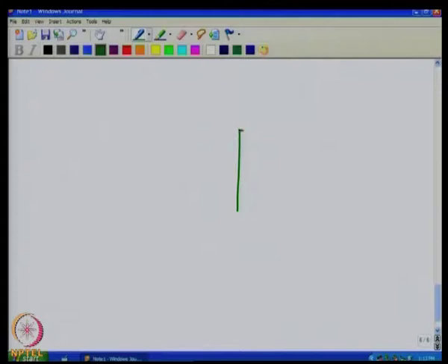For the resistance case, we just saw that the drops across the resistance can cause a functional problem in the output, where a current flowing through a track resistance can get coupled to the output and cause a deterioration in the regulation of the output. Likewise, you could have a problem with the capacitance and inductance too. Now, let us say, for example, you have a digital circuit like this.